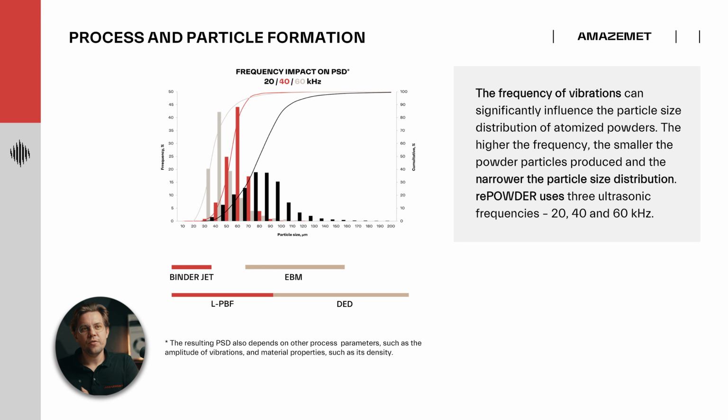In gas atomization, usually the particle size distribution is broad. We are getting both so-called fines and oversized particles, while the useful cut for LPBF is just a fraction of what we are getting out of the system.